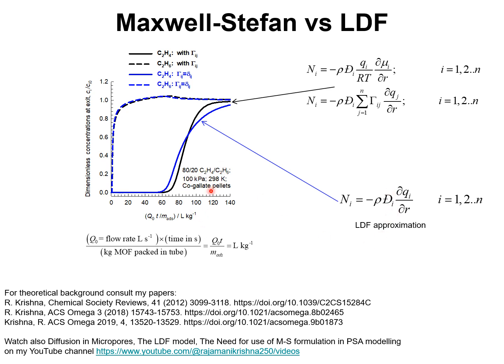For 80-20 mixtures, the simulations for the adsorption cycle using the Maxwell-Stefan formulation are shown in the continuous black line and the dashed black line here, whereas the simulations using the simplified LDF approximation are shown by the blue line.